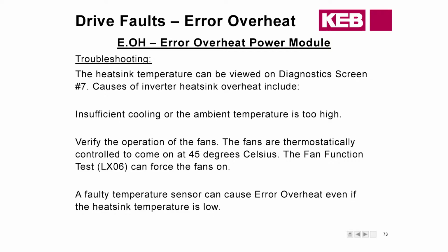Another thing that you can look at if you're getting this error is the actual heatsink temperature. That should be on diagnostic screen number 7. And you can verify this with your hand, use common sense. What does diagnostic screen number 7 say? If it says 150 degrees Celsius and you put your hand on the heatsink and it's cool to the touch, well, okay, there's an issue with the measurement circuit in the drive. So that's something that you can do as well.